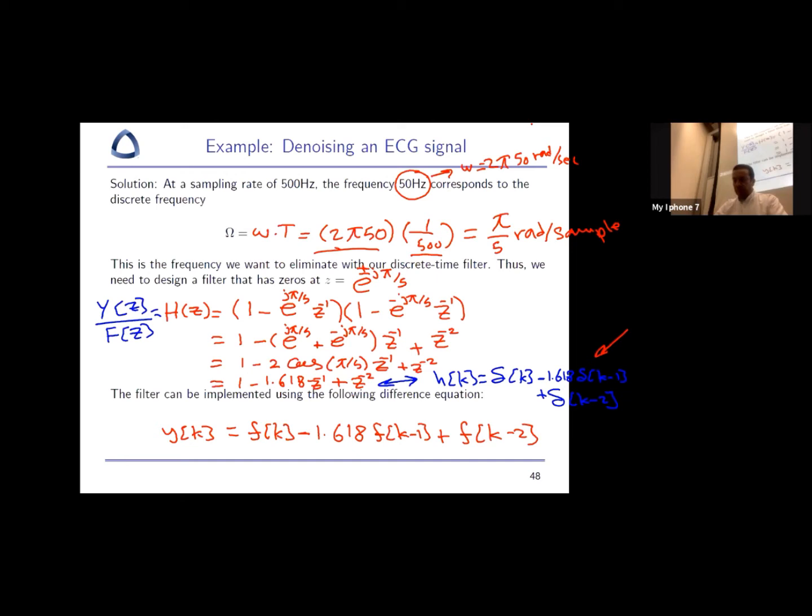This is the filter. We might need to do DC correction. This is before DC gain correction. You remember the correction that we used to do to adjust back the amplitude? We want this filter to have a unity gain, so it doesn't amplify or attenuate the amplitude. We just want to reject specific frequencies.